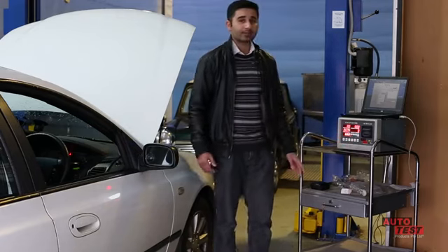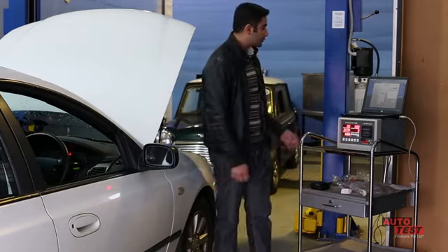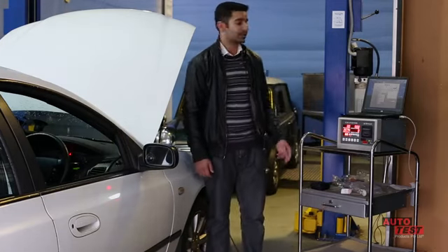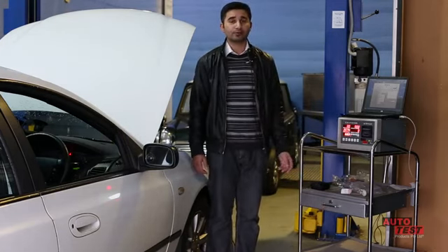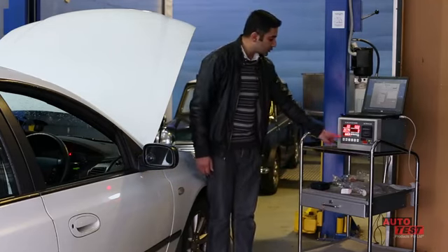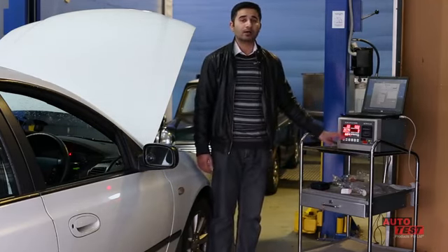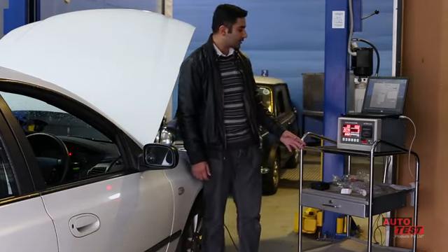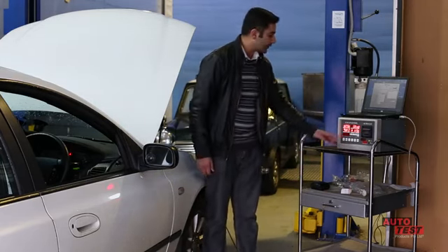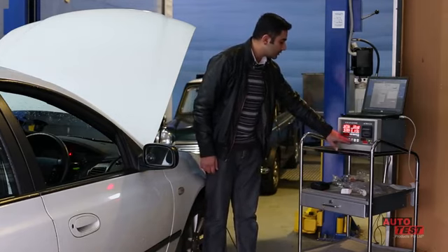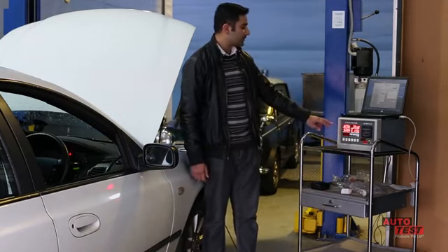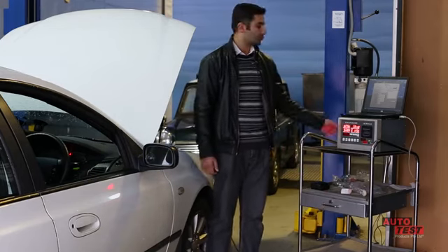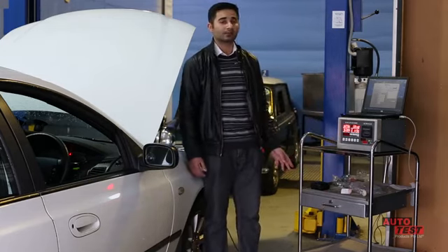Okay, the next thing we need to do is start this smoke test. There are two ways to start a smoke test. One is through the PC software, which we're going to do now, and the other option is to use the test option on the gas meter. If you press test, it will display the test menu, and if you scroll down until it displays smoke test, then press OK, it will start the smoke test through the gas analyzer without a PC.